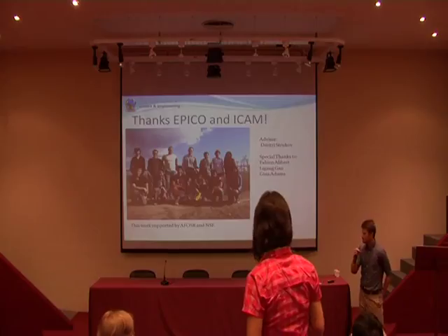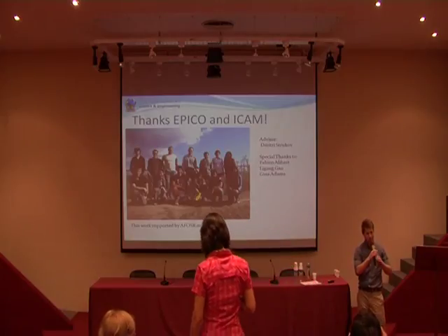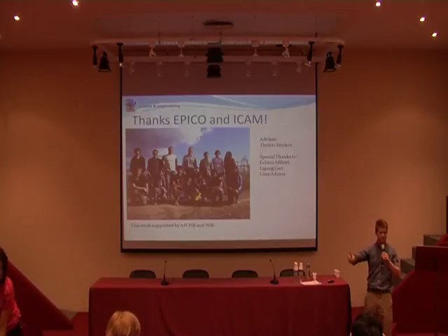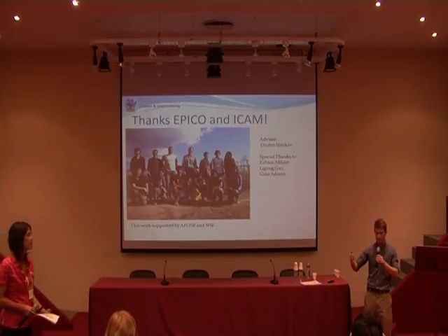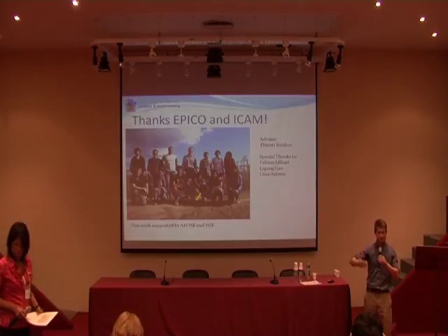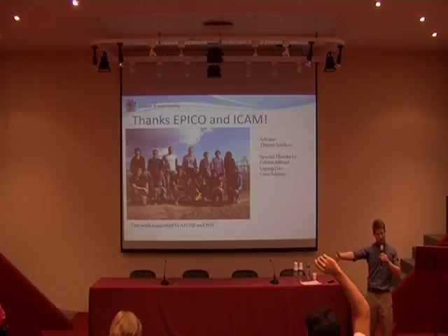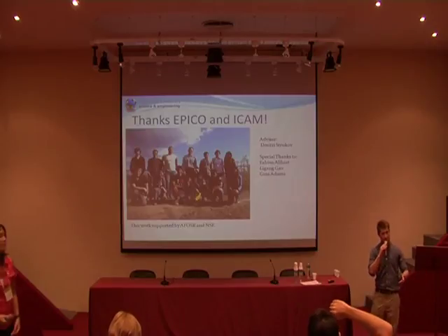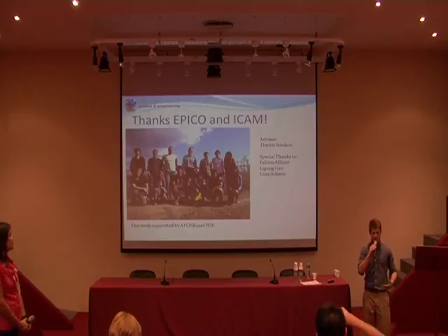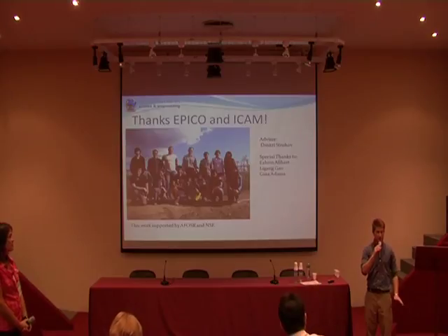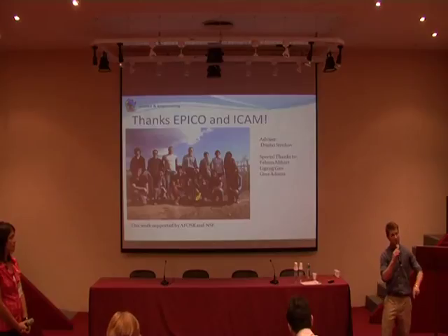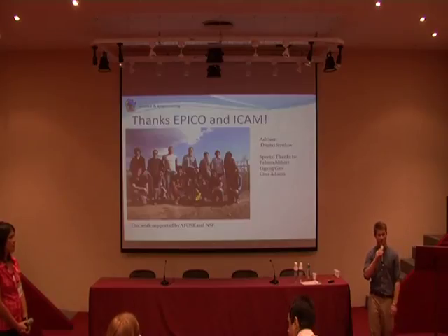And in general, once you figure out an algorithm for how to do it, and that takes a long time for each film in particular, because each time it's a different film, and each time you have to figure out more or less the voltage compliance associated with the forming. So when you're trying to figure out how to form the devices, you burn almost all of them. But once you figure out what you're doing, you can more or less get, I'd say, most of them to switch. The only problem is that some of them will be significantly better than others. So in terms of quality of every device, that will have low reproducibility.